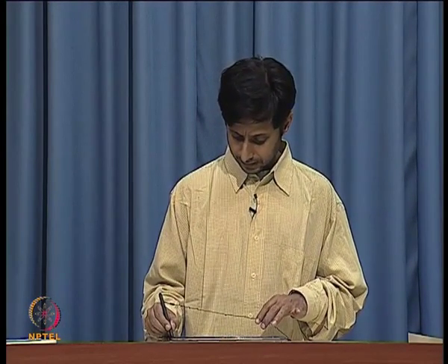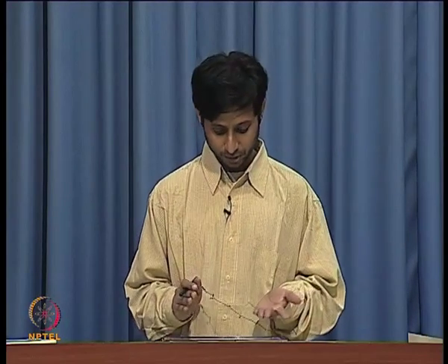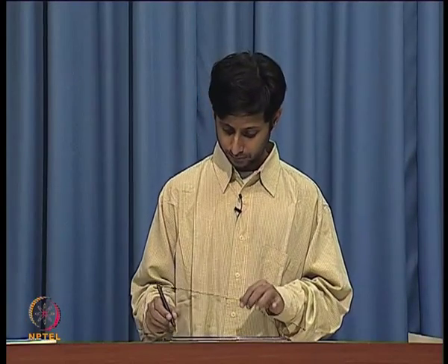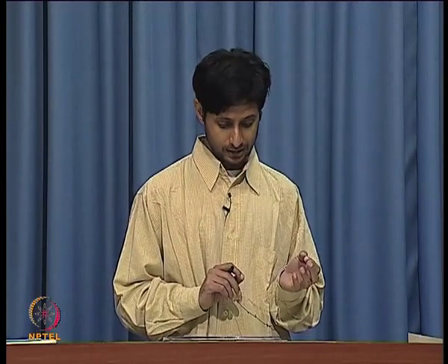All right. So, the first noise source, the first MOSFET, you could choose to think of it as a noise source, do the proper analysis and get lost in all of the calculations. The second approach is to have an understanding that at the matching frequency, the inductors together are such that the source resistance matches with what you see looking into the gate, and with that approach we computed a noise figure.